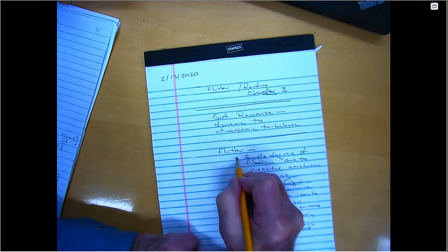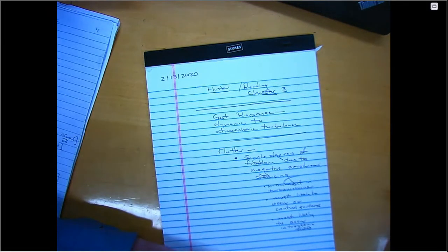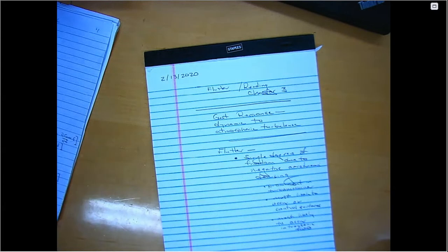So if single degree of freedom flutter is one kind of flutter, the only other possibility is multi-degree freedom flutter. But often you only need 2 degrees of freedom to describe qualitatively what's going on. You may need a dozen degrees of freedom in your analysis to get a good quantitative estimate of the flutter condition. But usually 2 degrees of freedom, or in some cases 1 degree of freedom, is sufficient to give you a qualitative indication.